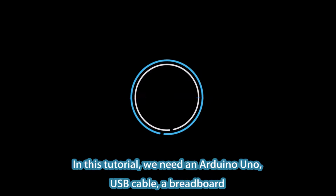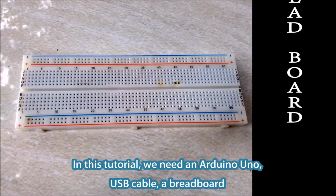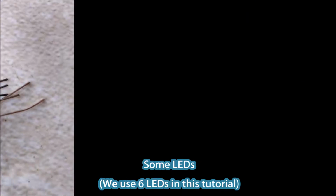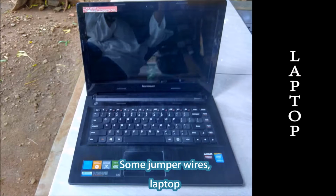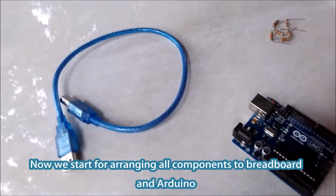In this tutorial, we need an Arduino Uno, USB cable, a breadboard, some LEDs, and we use 6 LEDs in this tutorial. Some 330 ohm resistors, we use 6 resistors in this tutorial, some jumper wires, and a laptop. Now we start arranging all components to the breadboard and Arduino.